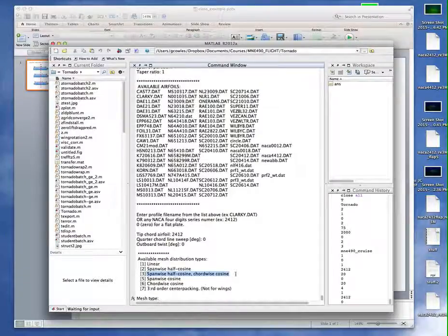There's different distributions you can use. You want to typically cluster the panels closer to the places of action, which is the leading trailing edge, and wing tip. So that's what is referred to here as a span-wise, half cosine, chord-wise cosine distribution. I'm going to use that for all your wings. It's a distribution 3. So everybody's using 20 panels across the half span, 20 panels across the chord, and a span-wise, half cosine, chord-wise cosine spacing. Mesh type 3.